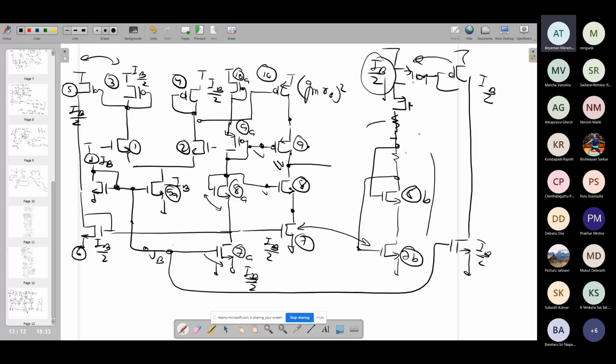So I didn't understand this part. Could you explain this again? We are using that reference voltage VB, and then what is this for? This is for biasing our cascode devices, right? So that's what we are trying to do over here.